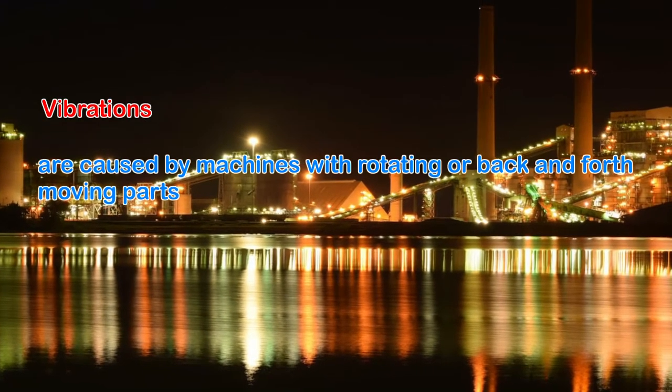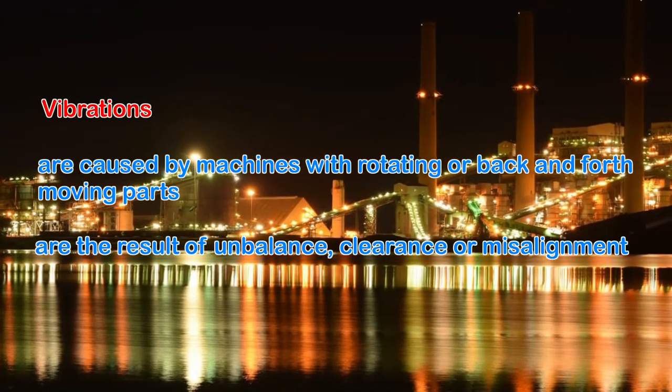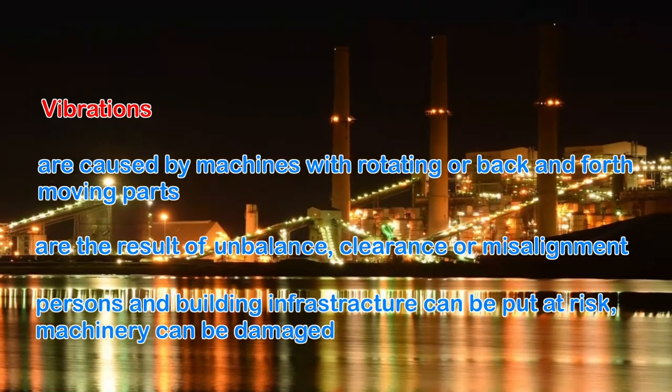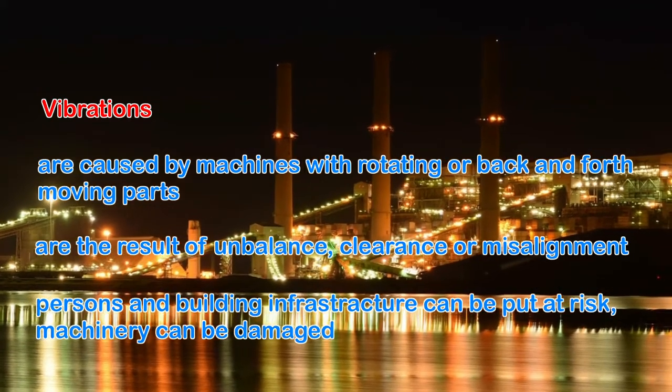Vibrations occur when masses rotate or move back and forth. Vibration can be an indicator of unbalanced rotors, bearing clearance or misalignment of shafts. Immediate action is recommended to avoid further damage, or even danger to persons, or building infrastructure.